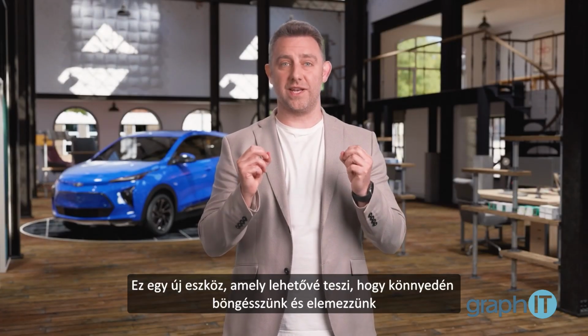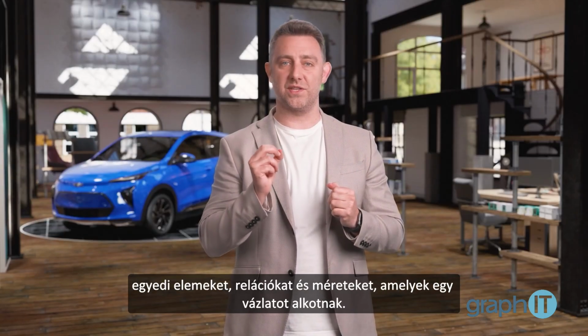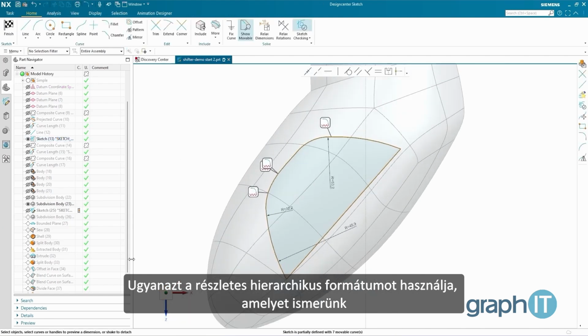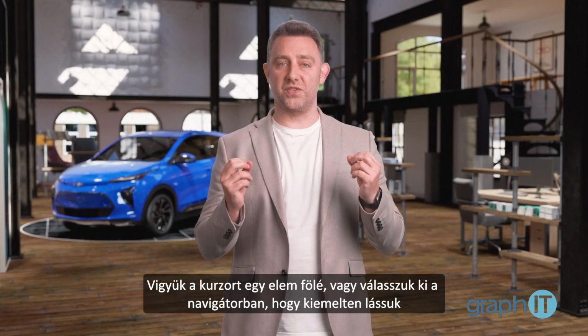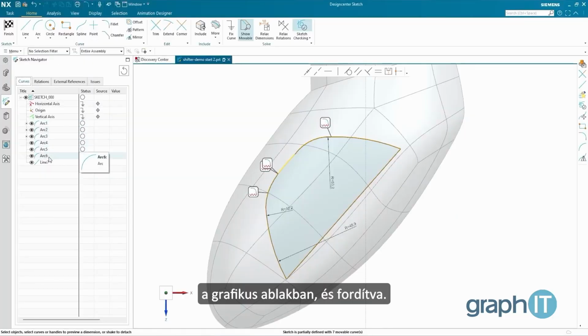It's a new tool that allows you to easily browse and analyze individual elements, relations, and dimensions that comprise a sketch. It uses the same detailed hierarchical format that you're familiar with from the Part Navigator and Assembly Navigator. So, getting started is simple and intuitive. Hover over or select an item in the Navigator to see it highlighted in the graphics window, and vice versa.